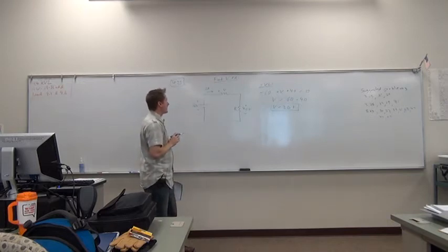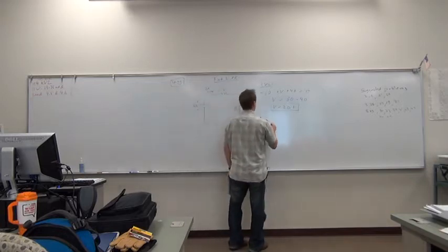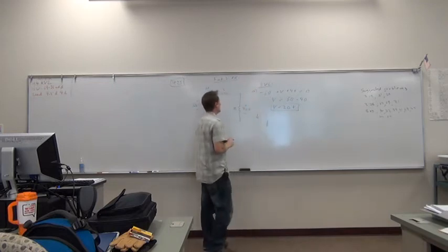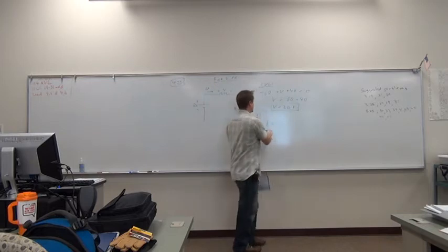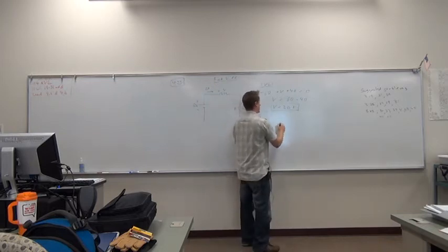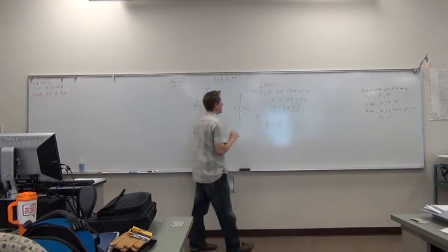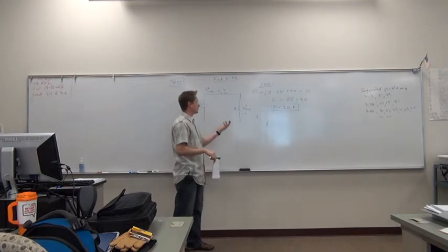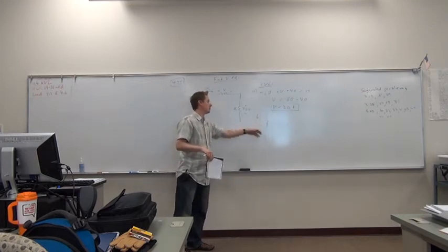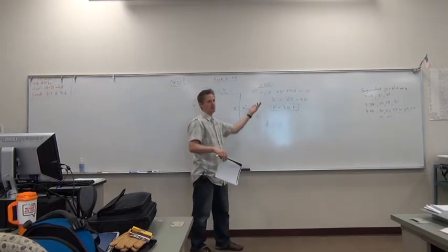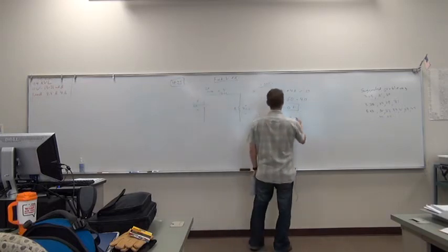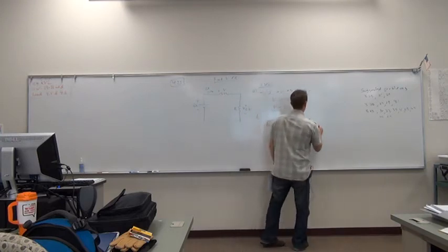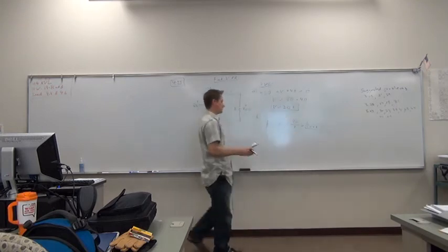And then it says find R. So R, the second part of the question, this would be the A part, I guess you could say, and then this would be the B part of the question. R is equal to, what does Ohm's law say? R is equal to V over I. Now the question is, do we know V and do we know I? And we do. We know I and we know V. So really, you could have solved this R part of the problem even without knowing this up here. You don't even need to know that. So this is going to be 40 over 2. It's going to be what? 20 ohms. And put a square around your solution.